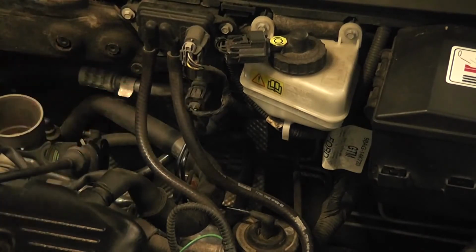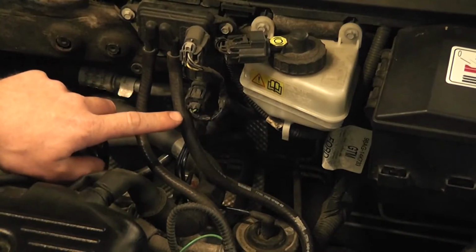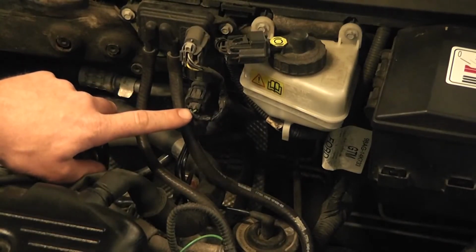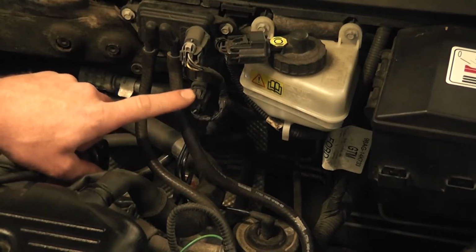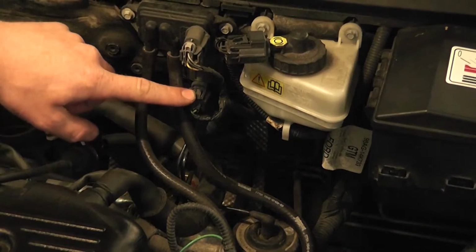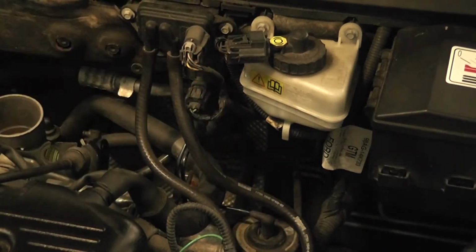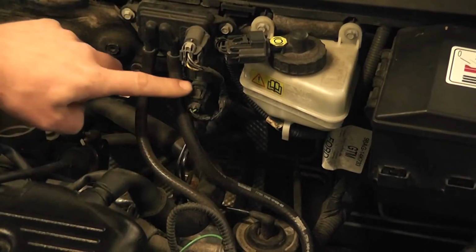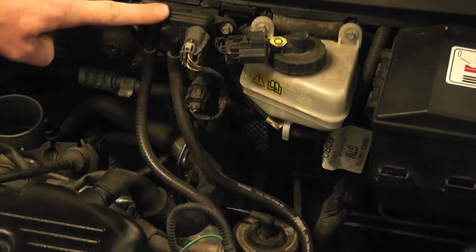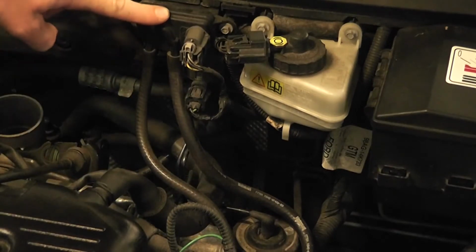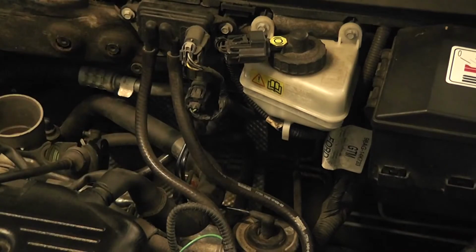This EVR solenoid we've talked about in some other videos I've done. It is ground side switched. It is a duty cycle controlled valve. The computer's going to control the on-off pulsing of this valve, which is going to control the amount of vacuum to the EGR valve, which is down here. So it is a vacuum controlled EGR valve. The computer controls the EVR regulator to open the valve, and the DPFE is going to report back the proper flow of the EGR system. So that's just a quick overview of this design.